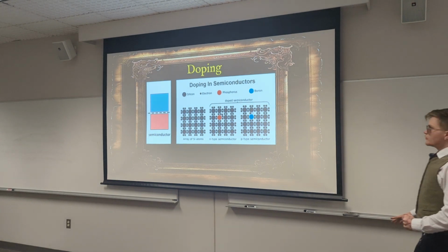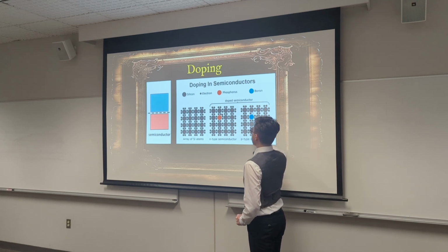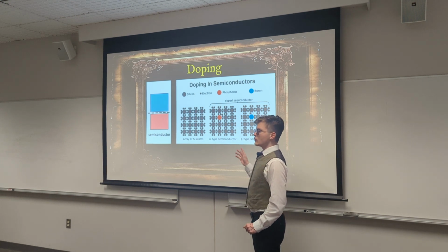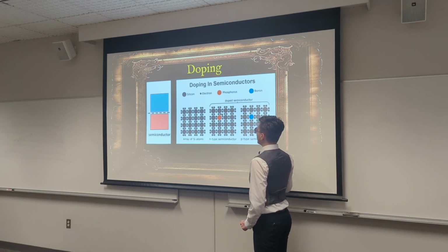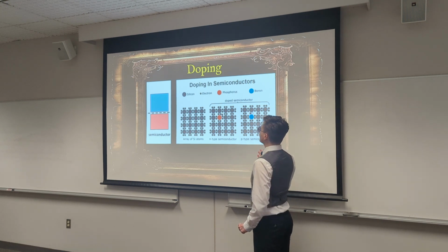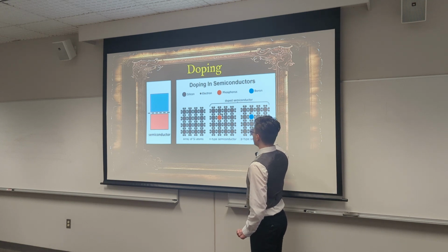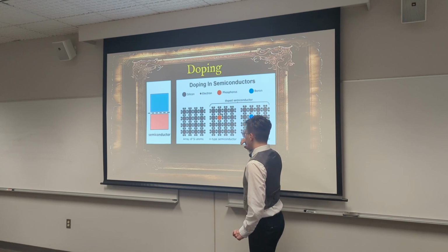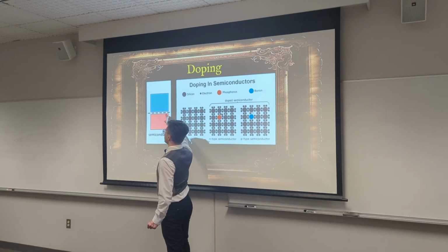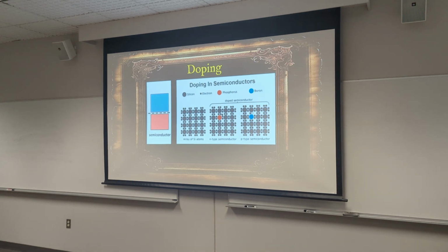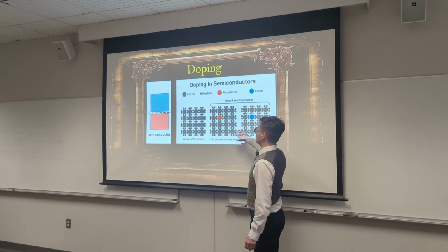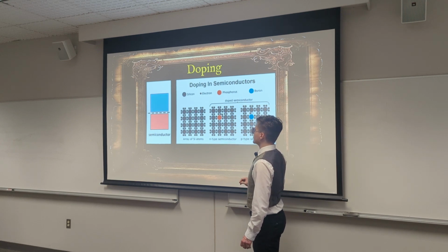And how doping works, we have a p-type material that we dope with group 13 elements, which gives the semiconductor extra holes. And holes are quasi-particles. They're not real particles, but we can think of them like real particles, and they are charge carriers. So electrons like to move between holes, and it actually increases the conductivity of that semiconductor. And it adds an extra energy level just above the valence band, in the middle of that band gap.